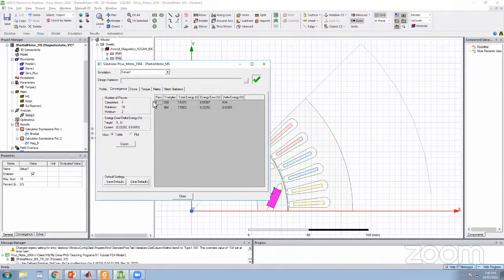It passed the test, and this is the total energy of the model, the total magnetic energy, which is B times H. Then the second time, it refined the mesh by 15%, meaning it increased the mesh element number by 15%. And this time, even though we refined the mesh by 15%, the total energy only changed a little bit. How much did it change?